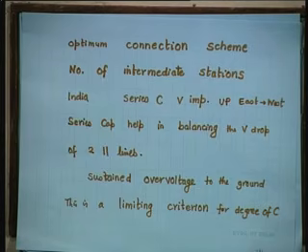Series capacitance is very important in India. Why? Any long line transmission needs series compensation, because in India, as I told you repeatedly, generation is always confined to the eastern part of the country, and most of the loads are in the western part. You can see the highly industrialized states are on the western side: Karnataka, Maharashtra, Gujarat, and the whole coal belt is the eastern belt, that is Bihar, UP, MP and Orissa and so on.